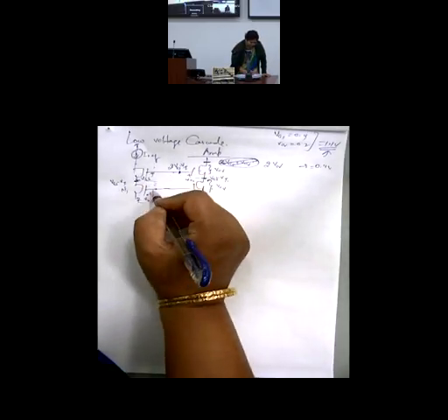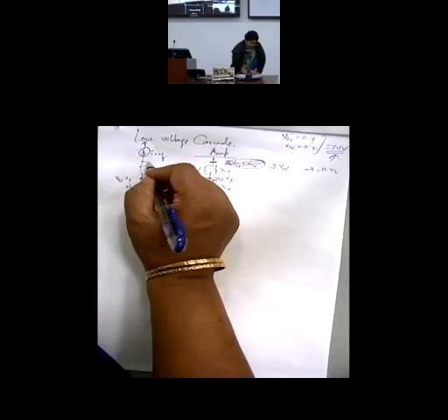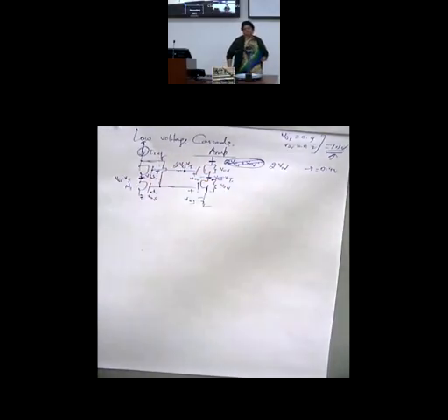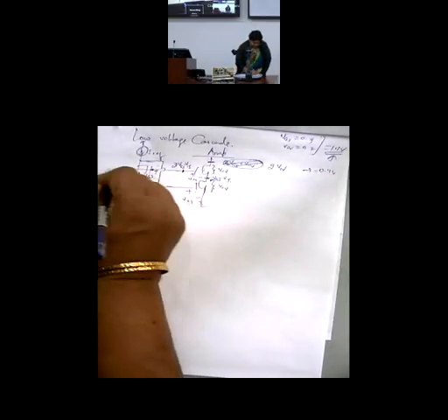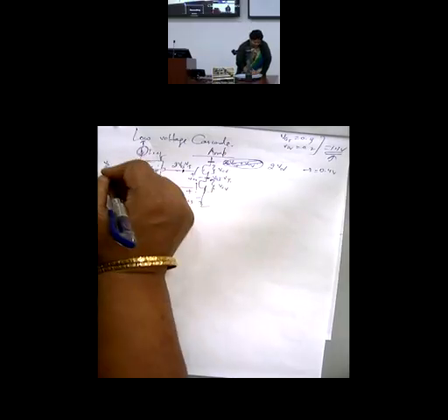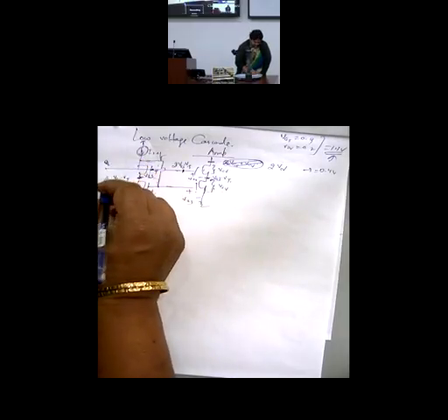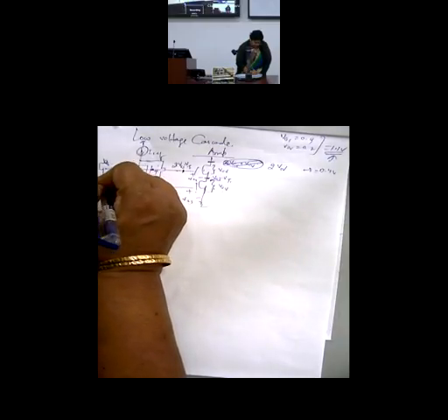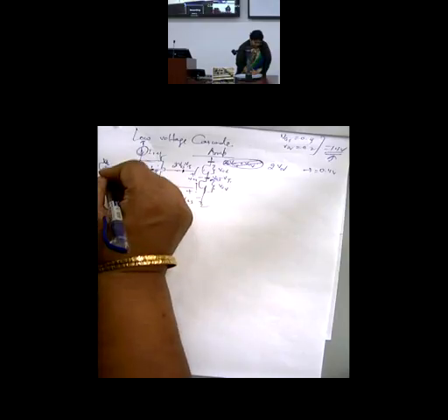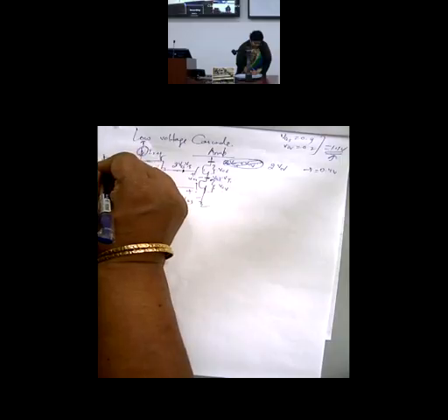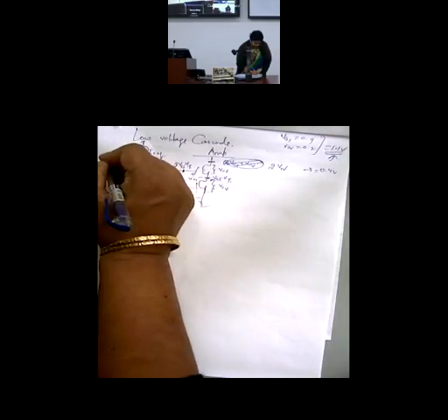So now to connect this, I'm making a connection which we did last time also, low voltage cascode connection. And I generate this potential 2 VGS minus VT separately. This is generated through an extra reference arm. I generate this extra reference. And here you put a resistor. This is VD. This is IREF.